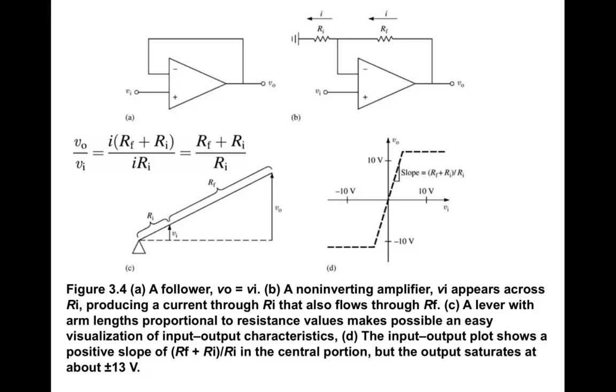The only disadvantage of this is you cannot independently necessarily select a feedback to input resistor ratio. So if the input resistance changes for whatever reason, your ratio might be a little more difficult to adjust. So once again, if the feedback resistor is, say, 2 orders of magnitude above the input resistor, then this is less sensitivity.